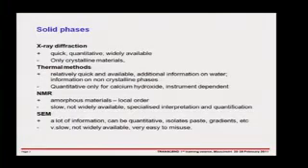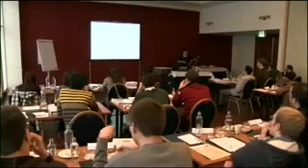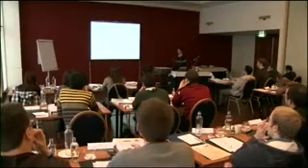It can be quantitative. The one drawback is that really you only get a signal from crystalline materials. And as we've talked about calcium silicate hydrate, we've seen that the major phase we want to often study is this calcium silicate hydrate, which is not well crystalline. Therefore, X-ray diffraction is not the perfect technique in this case.